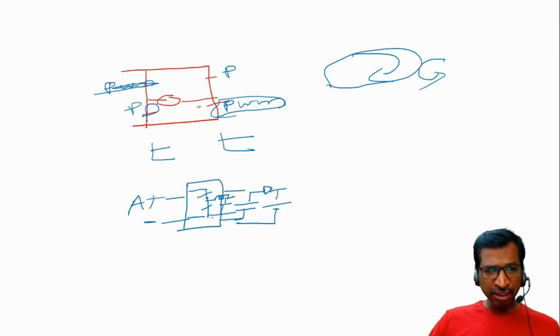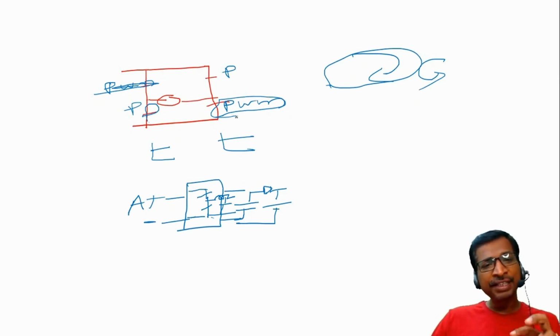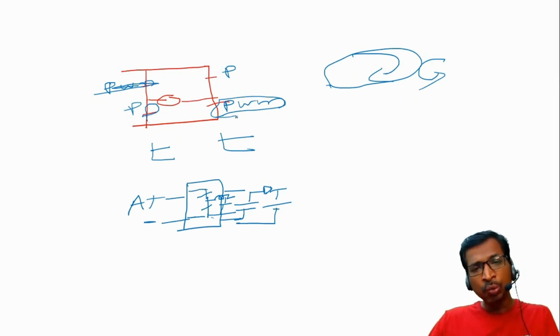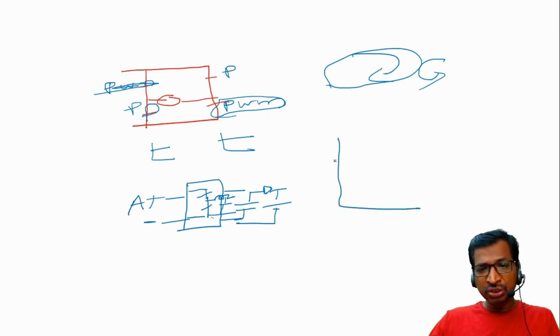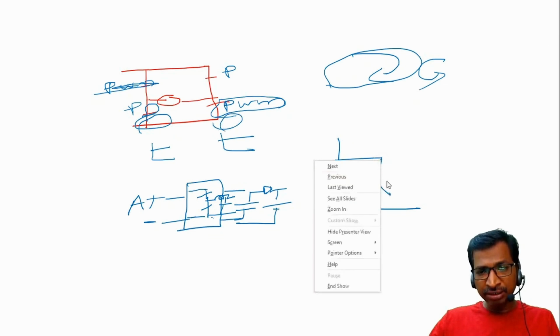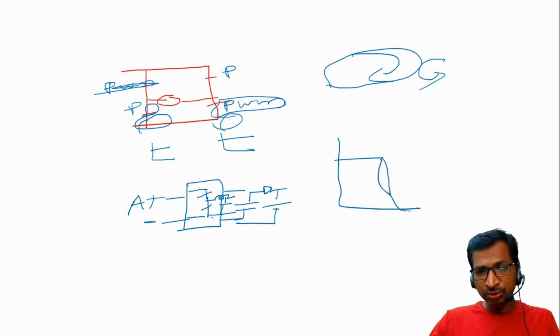See here, this is also regenerative braking, but we are dissipating the generated voltage within the loop itself. In that case, the speed will be reached straight away. For example, if it is a forward direction and you are enabling these two switches, in that case the speed will drastically reach the 0 position.